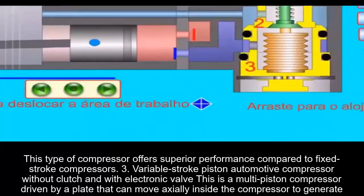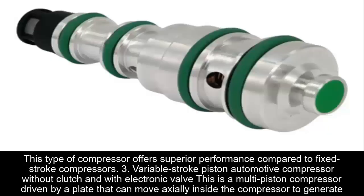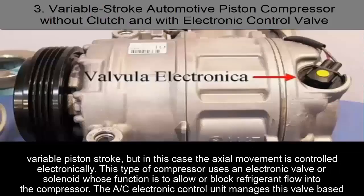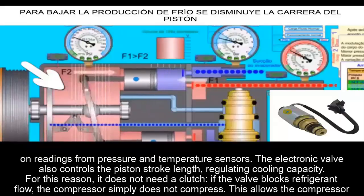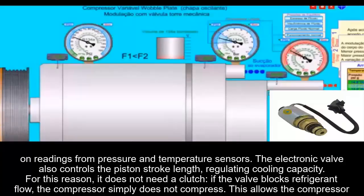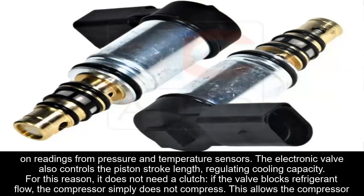3. Variable stroke piston compressor without clutch and electronic valve. This is a multi-piston compressor driven by a plate that can move axially inside the compressor to generate a variable piston stroke, but in this case, the axial movement is controlled electronically. This type of compressor uses an electronic valve or solenoid whose function is to allow or block refrigerant flow into the compressor. The AC electronic control unit manages this valve based on readings from pressure and temperature sensors. The electronic valve also controls the piston stroke length, regulating cooling capacity.